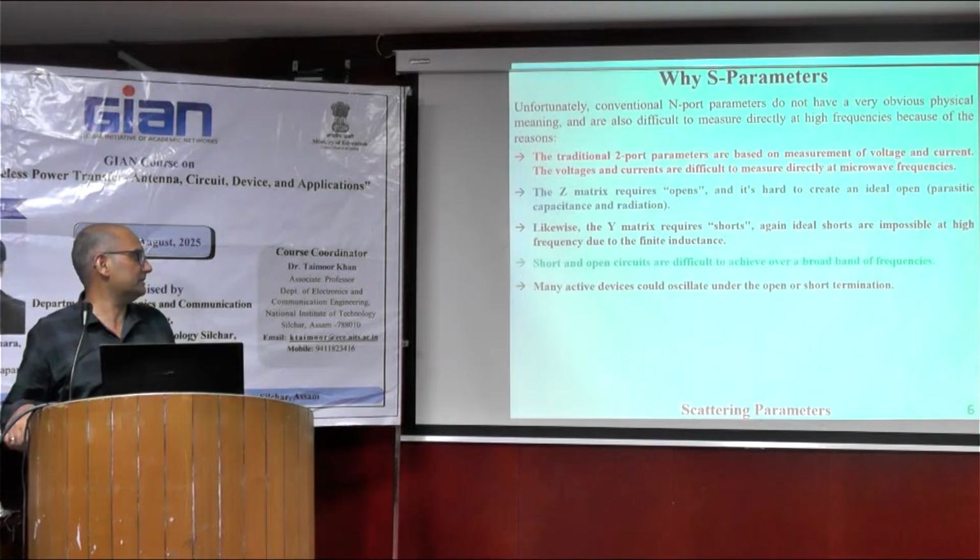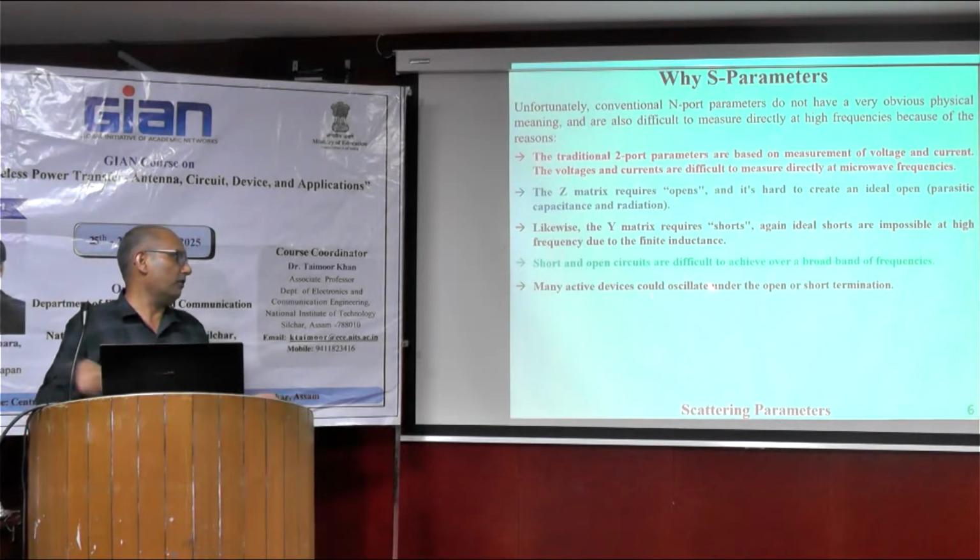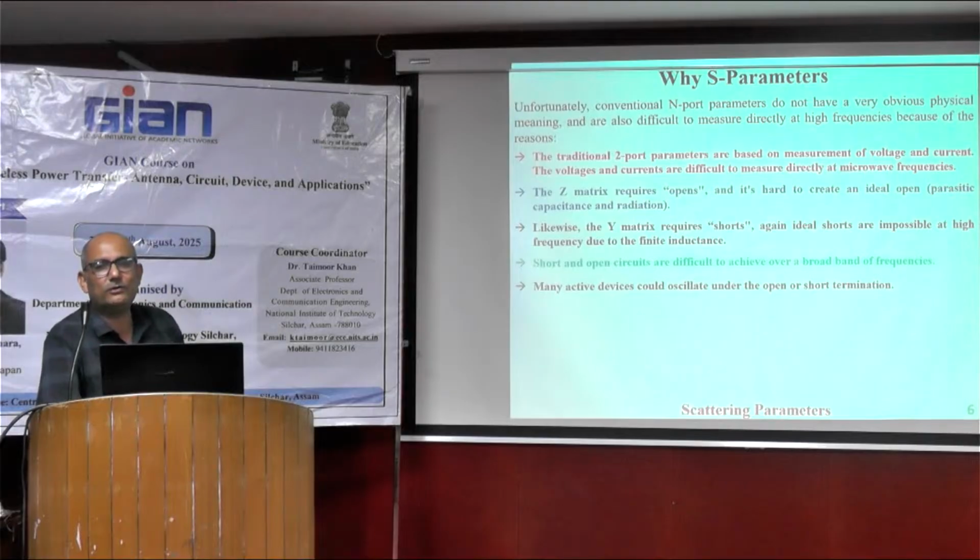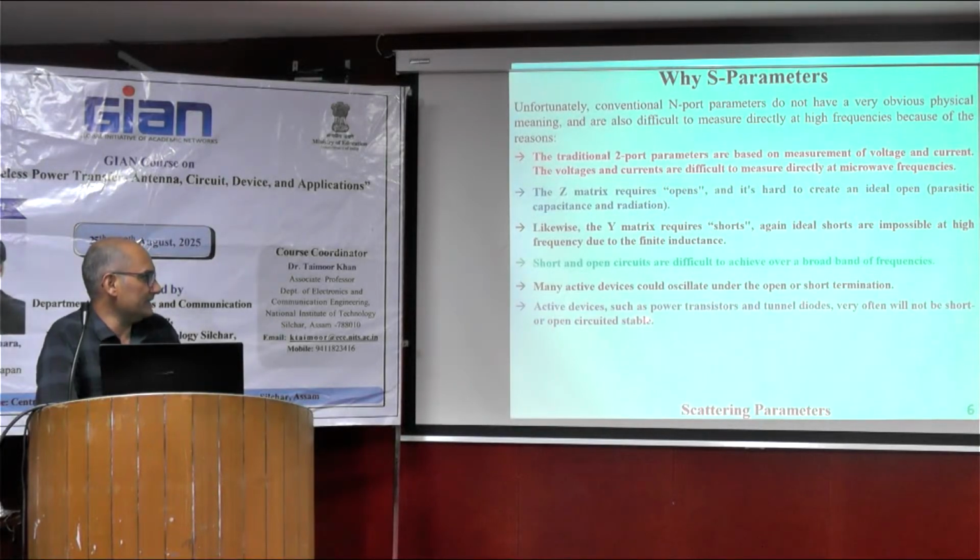These are the few points, and many active devices could oscillate under open and short circuit termination, which you can recall from standing wave pattern behavior. Short circuit and open circuit conditions we generally study in transmission line theory. That also occurs when we apply open and short circuit termination. Active devices such as power transistors or tunnel diodes very often will not be short or open circuited. Stability is another issue: these active devices will not be stable if you apply open and short circuit conditions.